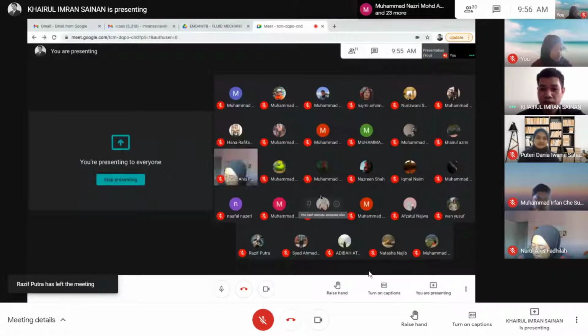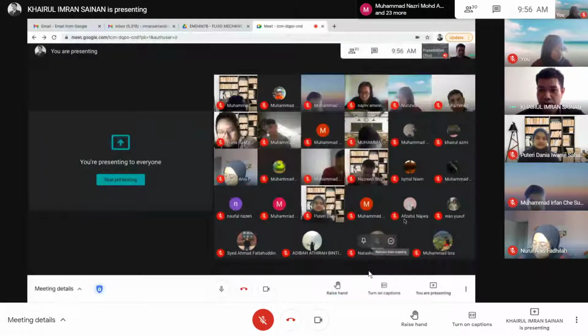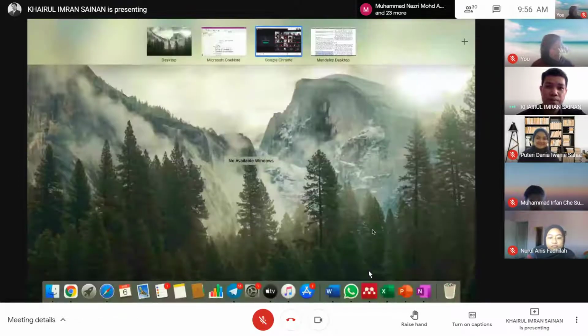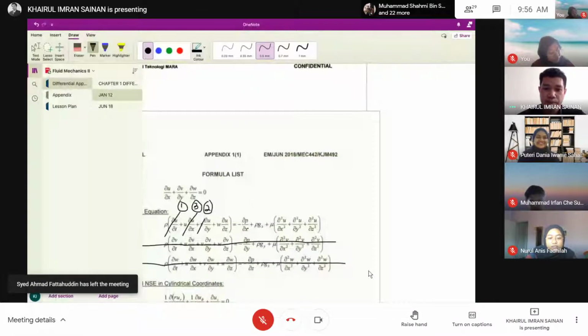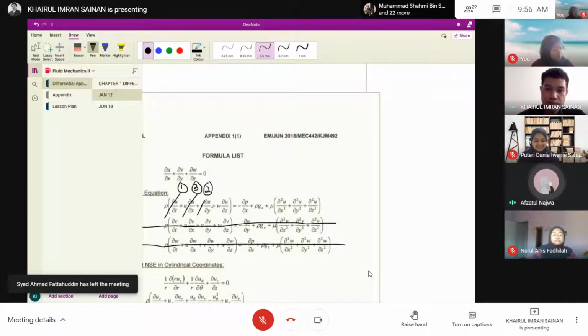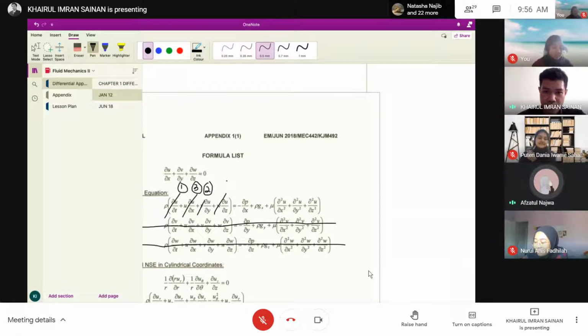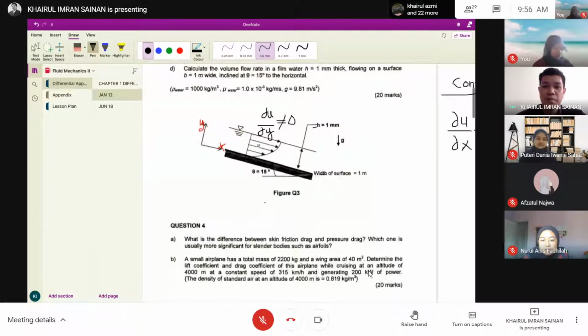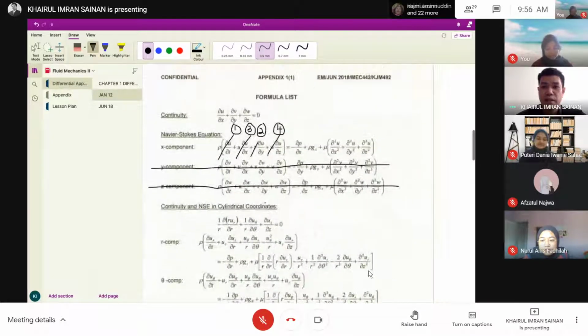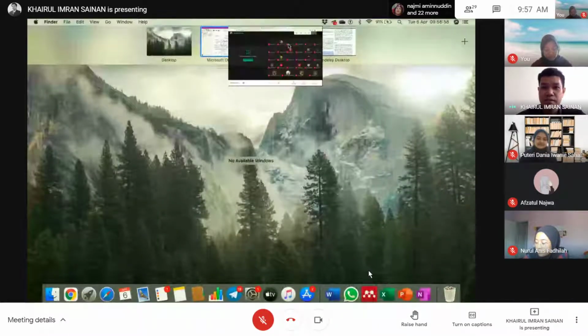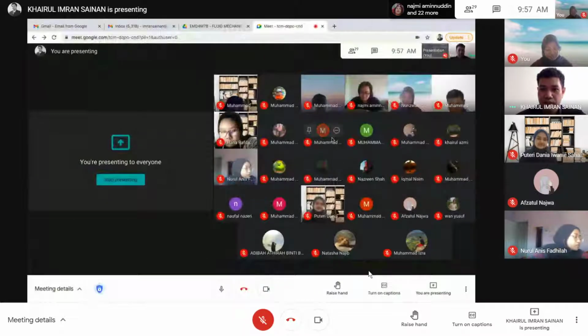The next term, del U over del Z. So Z. Cancel out. Because of number 4. No flow in Z direction. Okay, next we go to the pressure difference. Del P over del X.